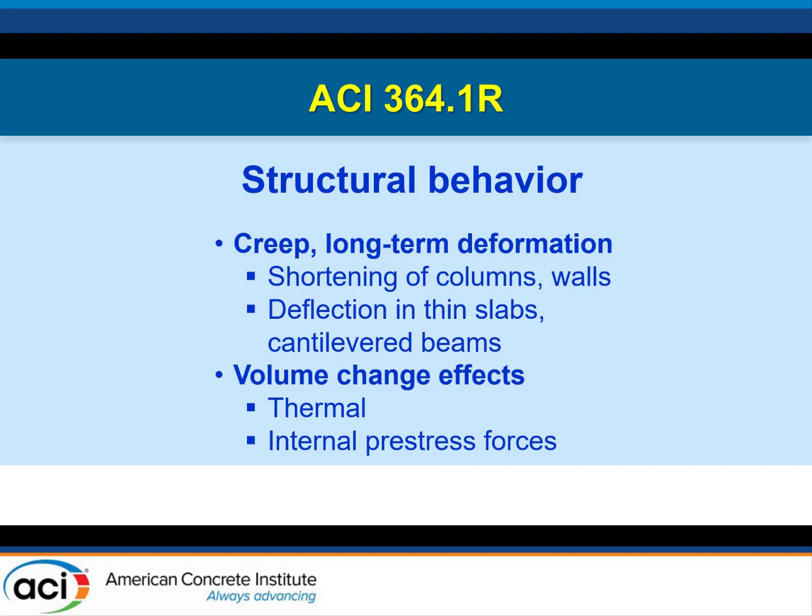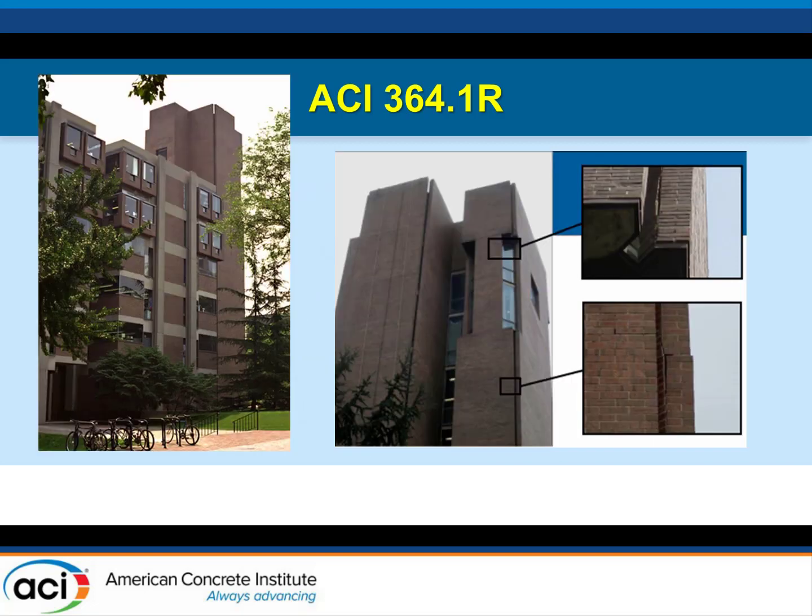Structures are designed certainly from a strength standpoint, but there are other factors that need to be considered in design. So creep, long-term deformation, particularly when you get taller structures that are going to shorten. You get volume change effects on the structures. These are more serviceability things that have to be considered in the design, but they factor into the evaluation.